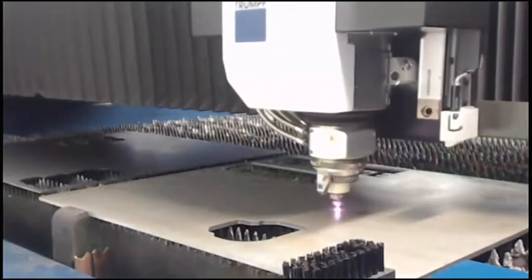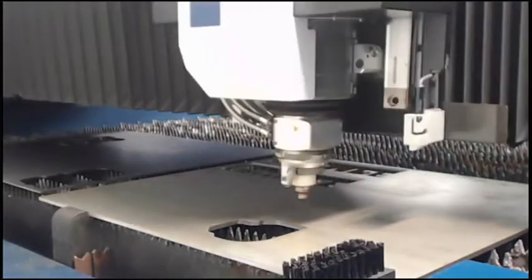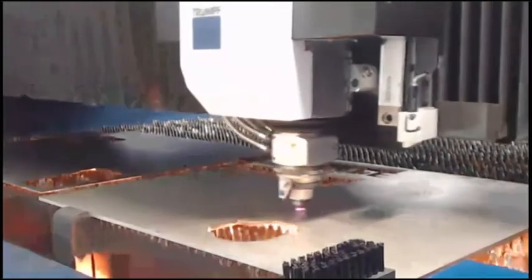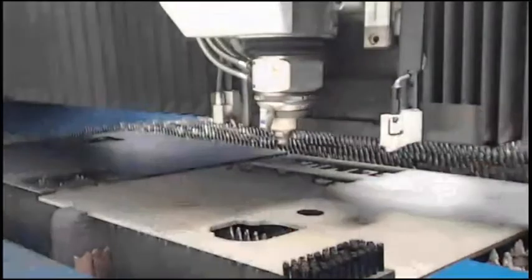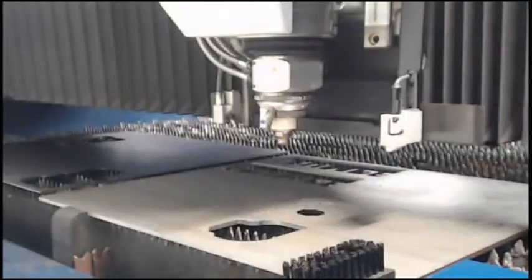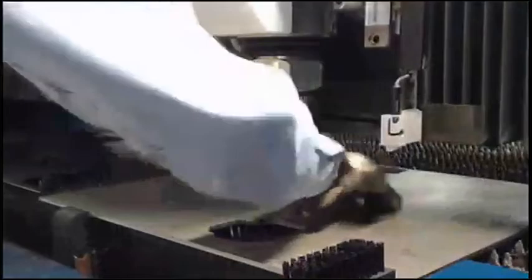You will see it do a nitrogen etch, so you'll see it purge the gas after it does its etch. So it's purging right there. It's going to put air into its gas chamber, and then it's off to cut. And like Brett was talking about before, you'll see this thing pierce right up in the air, which we call fast piercing. It gives you a pierce time that is almost 0, if not 0. Let's pull this out of here. Oops.